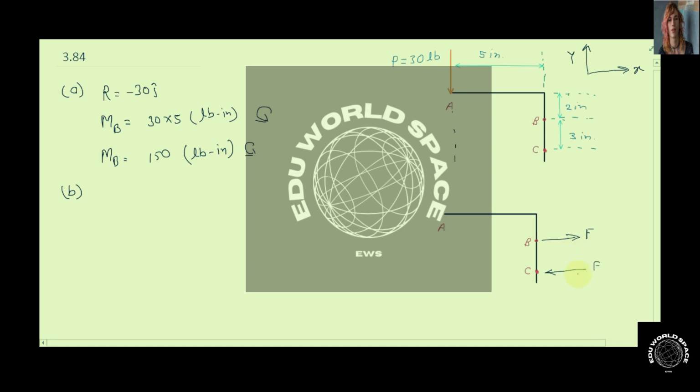So these two horizontal forces, the couple, must cause the same moment that is caused at point B. So if we calculate the moment because of this force system, that will be F multiplied by the perpendicular distance between them. So in the equivalent system the moment will be F multiplied by 3, and in direction it is going to cause a clockwise couple. Alright, and this must be equal to the moment already present at point B in the equivalent system, and that was 150 pound inch in anti-clockwise direction.